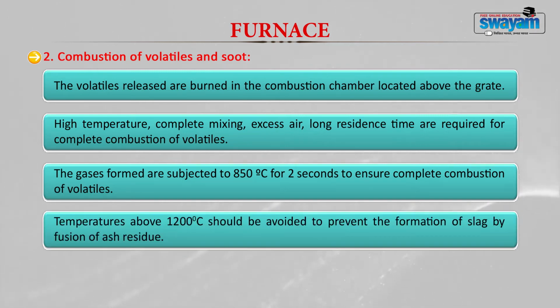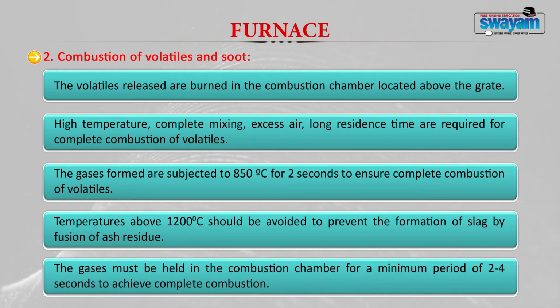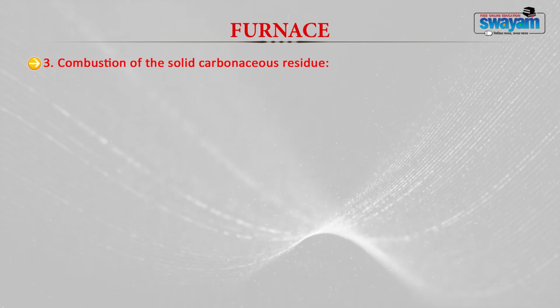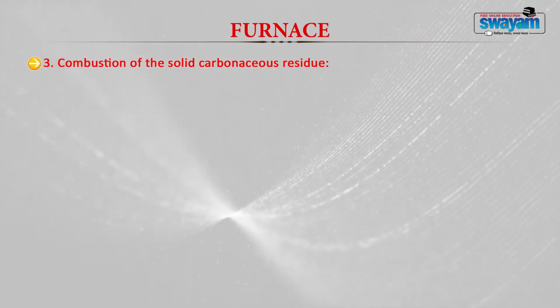Now, temperatures above 1200 degrees Celsius are generally avoided to prevent the formation of slag by fusion of ash residue. The gases must be held in the combustion chamber for a minimum period of 2 to 4 seconds to achieve complete combustion.